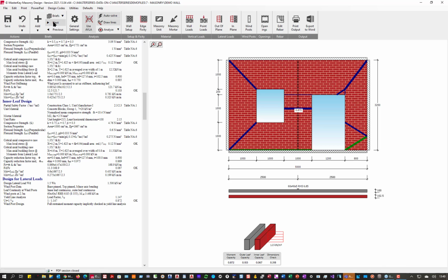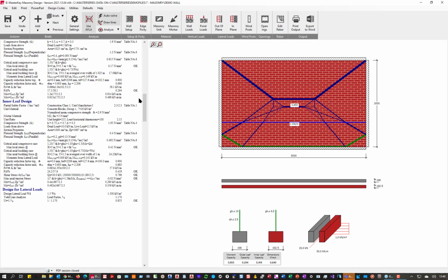We actually can do more than that. Those would cover your general facilities and features that you want. What we have here is a wind panel that has a wind loading plus a 1 kilonewton per meter surge load, a horizontal line load, pushing against that. So some sort of barrier or something, or attachments for racking in a warehouse can be made.